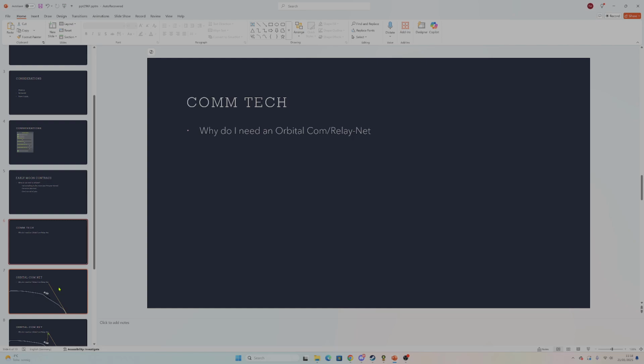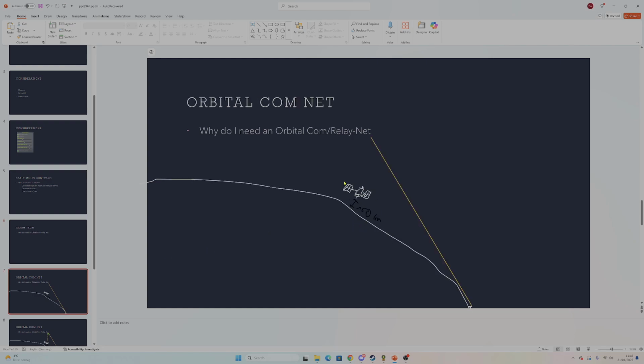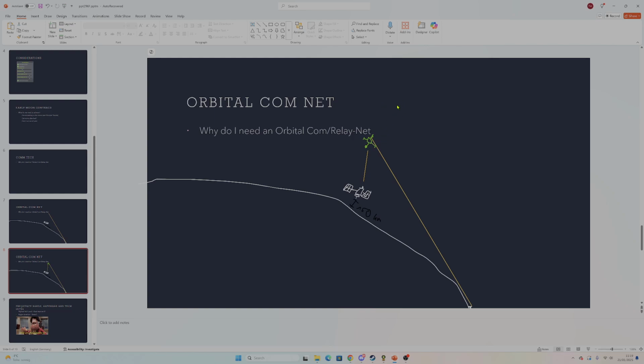It's pretty simple. So, my best drawing, I tried my best drawing skills. You're in a low parking orbit, at like 150 kilometers, for example, and you have a ground station. Due to the Earth's curvature, I know it isn't flat, but since it isn't flat, you can't reach it. There's some geometry here, so you can see that you can't actually see the ground station, so you can't communicate with it. How do you fix it? You have a satellite that's way higher up, usually like 20, 30K up, that is able to see the ground station and to see you, and then communicate with you. Your space probe will communicate with that relay, and that relay will get back to the ground station. So you have a reliable data connection.